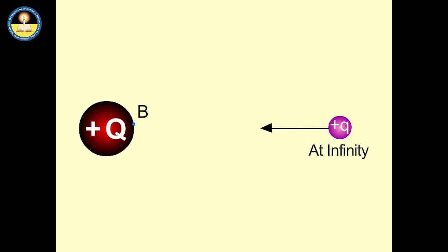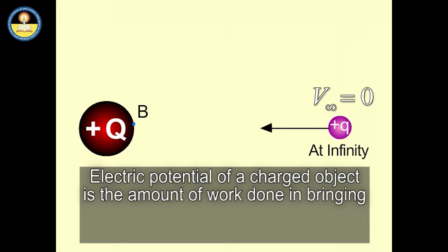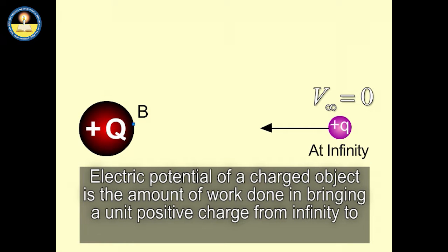This equation is a mathematical statement of Joule's law of heating. Thus, Joule's law of heating states that the amount of heat produced in a given conductor when current flows through it for a fixed time is directly proportional to the square of the current flowing through the conductor. It implies that if the current is doubled, the heat produced will be 4 times, or if the current is halved, the heat produced will be 1/4.